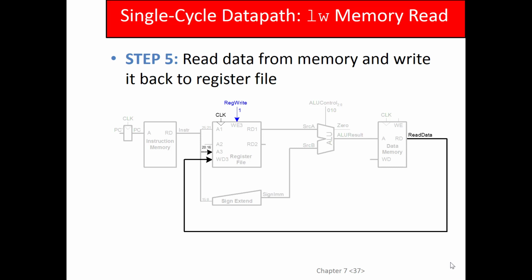If you're confused by looking at this, which you easily could be, because it's just a bunch of blocks with wires, you really have to think of these as memory, and you have to start here and read from the left to the right. And you have to understand how all these memories work, and this is all happening in one cycle. This is a single cycle CPU. The only thing that changes on the clock edge is the program counter, and everything follows suit from there. Well, actually, this register file is also synchronous, because the writes are synchronous. So everything begins with that and ends there on the clock edge. You guys with me?